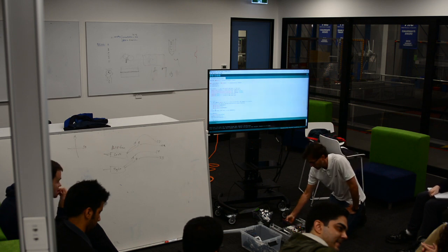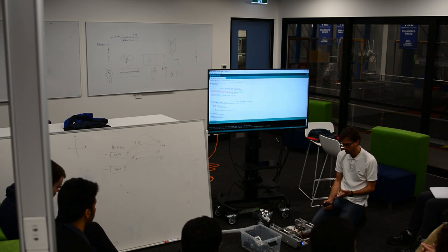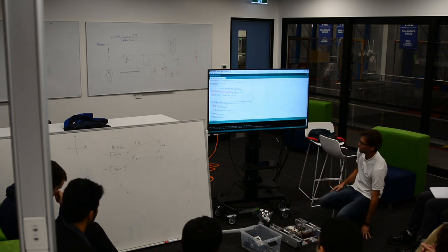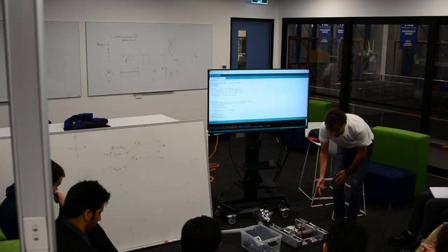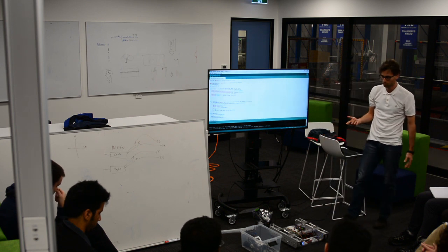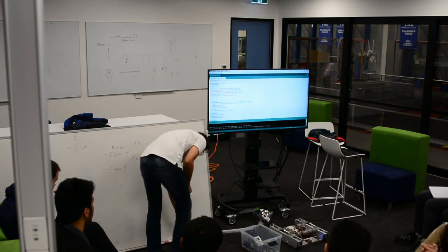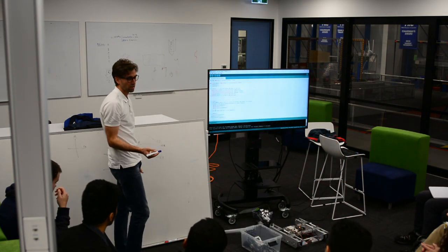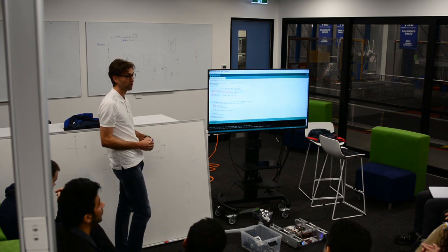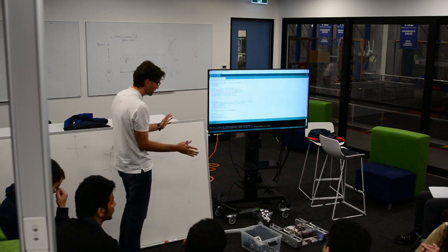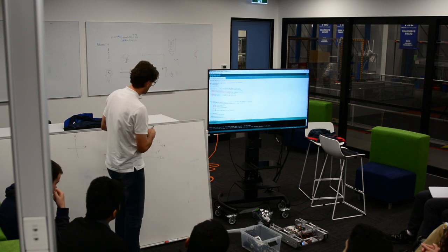Okay. One thing we're definitely going to need is to turn the robot on, so we're going to have to power it up. And then we're going to have to figure out a way to talk to the motors. Now, I'll show you how that's done. You might not need to know how this is done, but these little white boxes are going to take the throttle signal. So we might define a variable called throttle, and the throttle signal is a bit strange. What would you think of as a stop throttle? You'd think you'd put out 0, right? Okay. We're going to put out 90. So we're going to talk to these as if they are 180-degree servos.